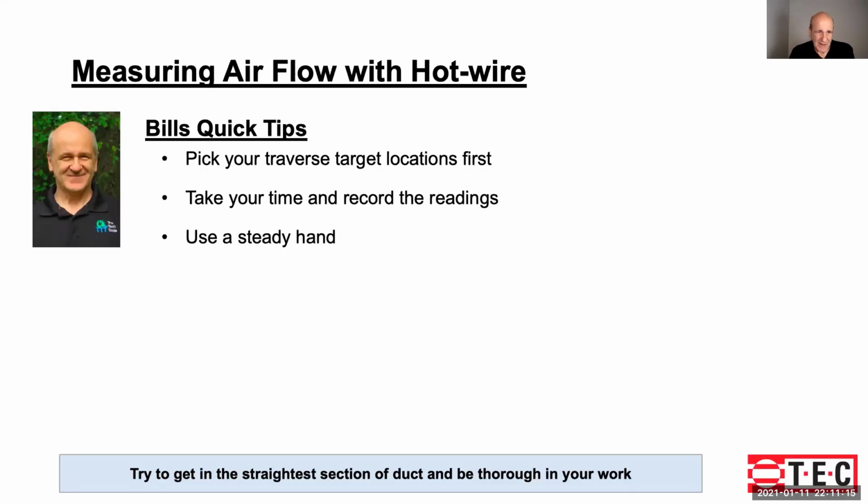We're going to be talking about measuring airflow with hot wire or thermal anemometers. Some quick tips: make sure you pick your traverse target locations first so you can concentrate on making a great measurement when you're doing your traverse. So have things marked off with a Sharpie, have your holes drilled in the right locations.